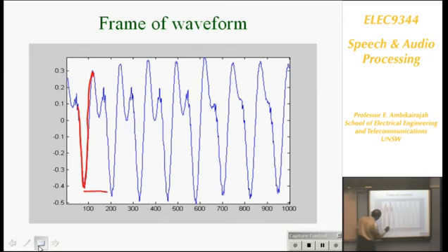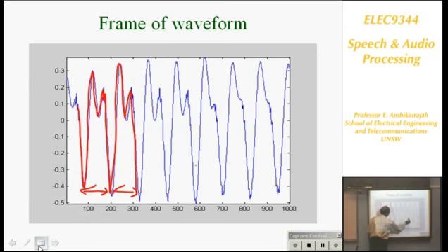And if I start to measure this distance, you will find that's the distance of the vocal cord vibration. Immediately I will say, this is a voiced sound, because I see these peaks. So you can see that when the vocal cord vibrates, that excitation hits the vocal tract, and the output waveform is the actual pitch. And these small bumps are due to the vocal tract resonance.